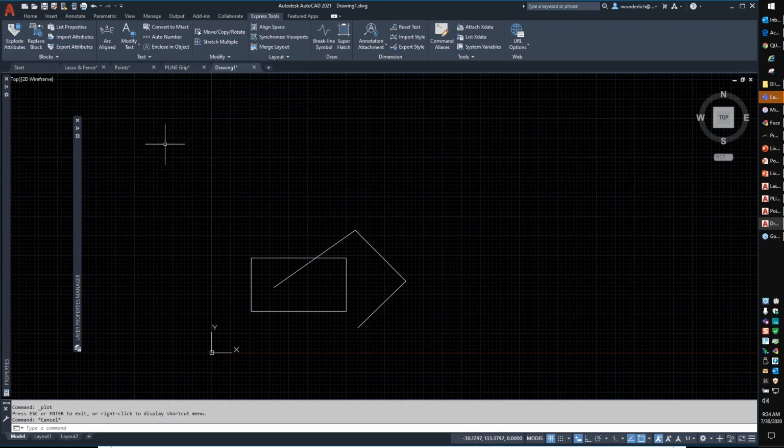If you're running AutoCAD LT, there is no way to do it easily in AutoCAD LT. We would need to write a script for that. I know there's a couple of scripts online that should flatten everything to a Z elevation of 0. There's a link to paste. Yep, Lori took care of that.